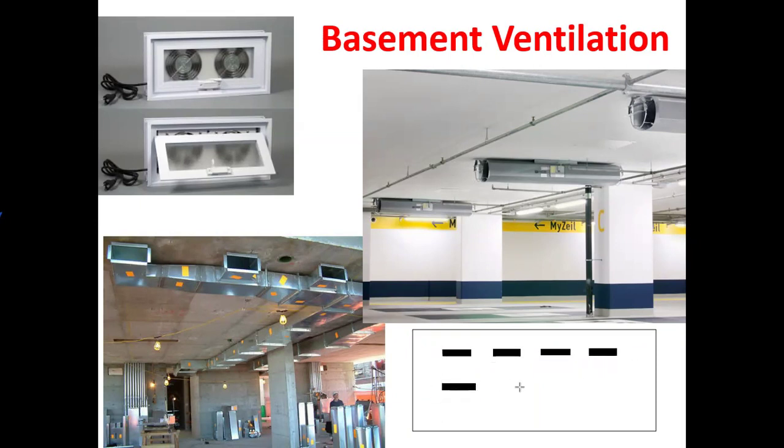Yeah, likewise. So these jet fans in this picture, you can see this now. This is meant to be the jet fans. Jet fans are placed across the basements according to the zonal concept. That means, for each area, it should be considered as some kind of zone. As I told you right now, the fresh air should be entering the area and flow across the area. Actually, these jet fans are equipped with two sides. One side is the suction side, and the other side acts as the discharge side.